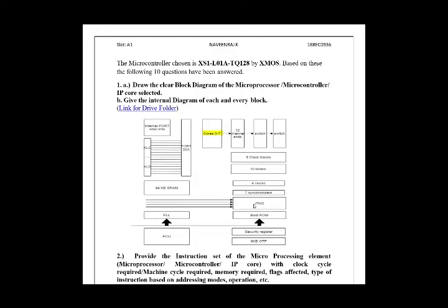The security bit 5 is 1. So now from the OTP port, the contents are transferred to the base of SRAM, and the program gets executed. This is the basic function, in layman's terms, of the boot ROM, read-only memory. We can't change it. That's why it's called read-only memory.